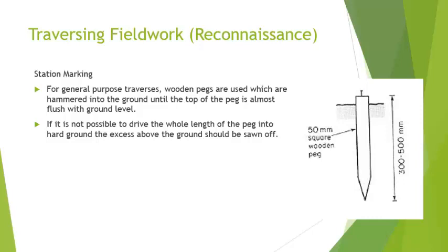The hole is much smaller, of course, compared to the pegs, but this is actually the benefit, because it allows the pegs to go deeper and sturdier in the ground. Once the peg is solid in the ground, a nail should be tapped on the top of the peg. A small piece of nail. The nail should be completely flush into the peg.